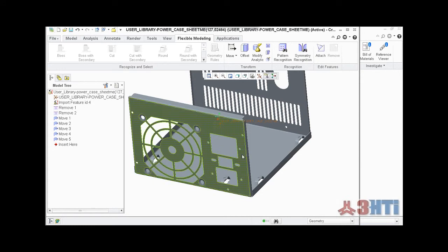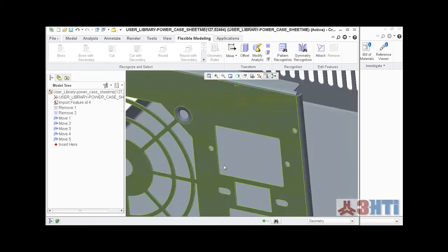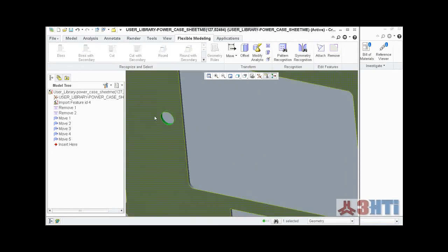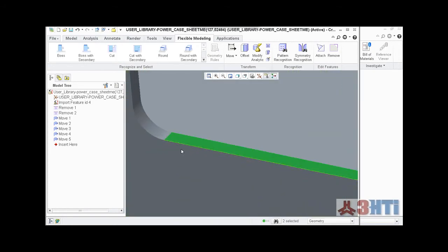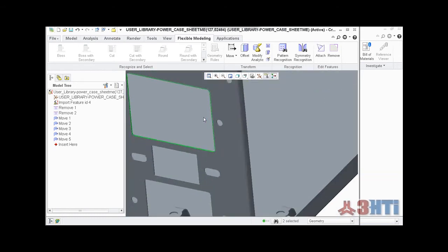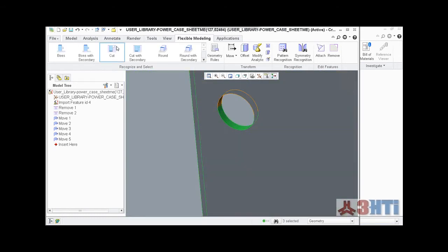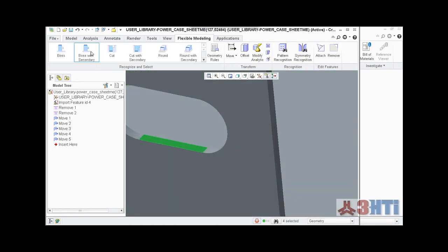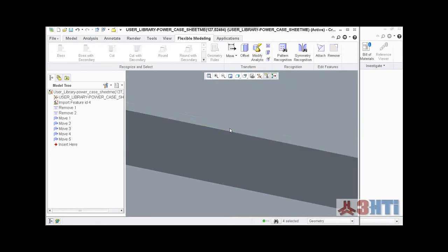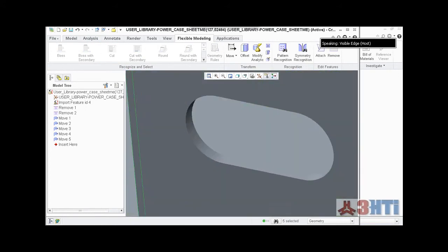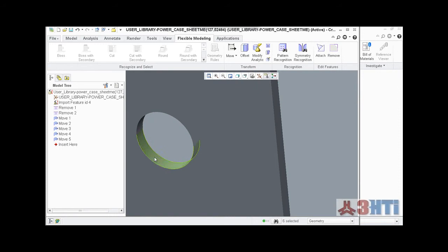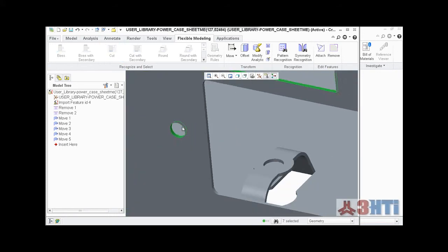So that obviously the sheet metal box is higher, so I want to move these cuts up a little bit. So I'm going to use, again, another move function, and I'm going to just grab these cuts. It's just involving picking the surface, recognizing it as a cut. And I'm just going to do this for all these surfaces right here pretty quick. Recognize this as a cut. Hey, we'll grab all these guys. It won't take too long here. This is a cut. Again, the software is recognizing the fact that it's a cut. It sees that it's part of some cut geometry. So it's recognized it appropriately.